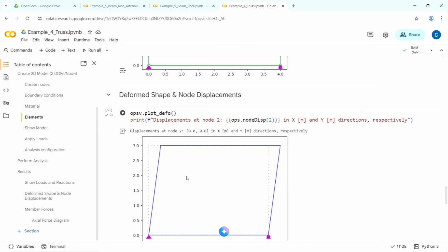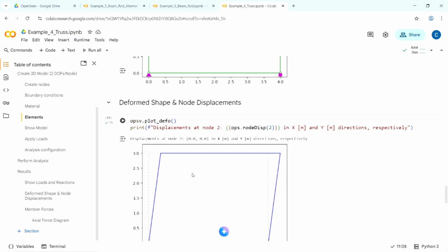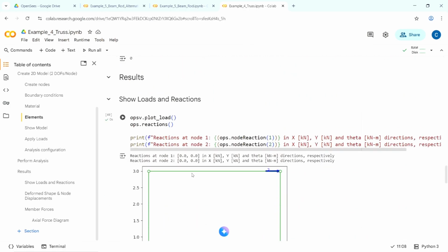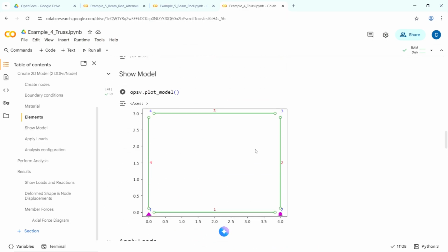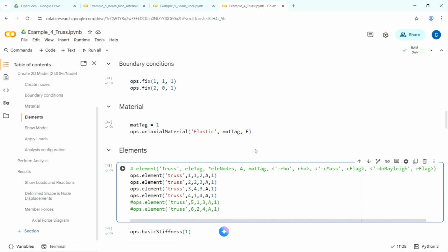The truss is going like this. It should have complained. Okay? I could not see anywhere it is complaining. Very interesting. But in the other case, when I made the structure unstable, it was giving a warning that the stiffness matrix is singular, but now it is not.